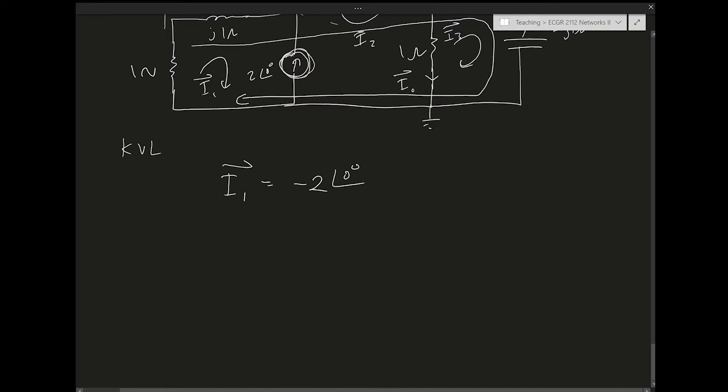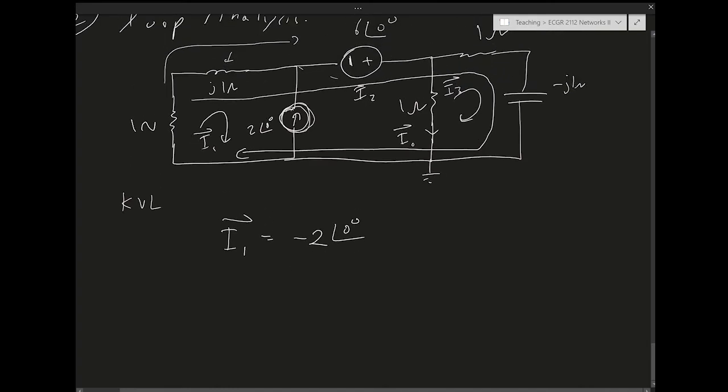So as I'm going through the loop represented by I2, I got the first equation correct. That's fine. I1 is fixed by the current source, because there's no loop selected here. But then when I'm moving along the loop represented by I2, in this portion I have both I1 and I2 passing through those two elements.